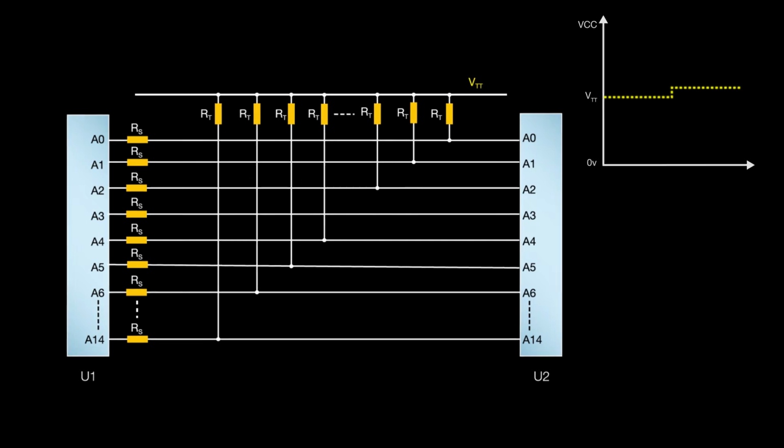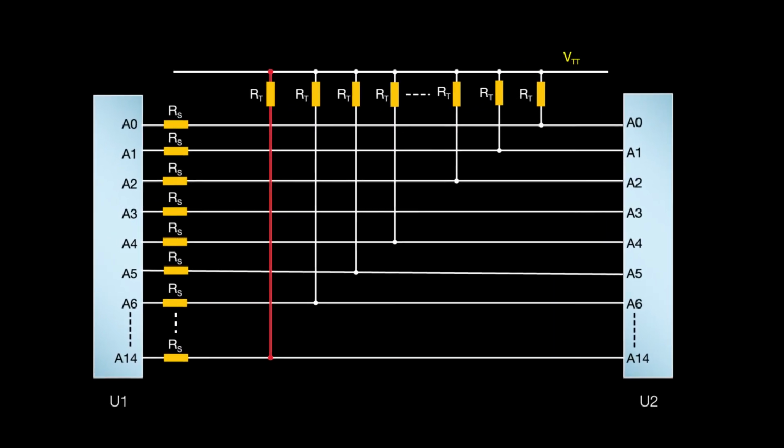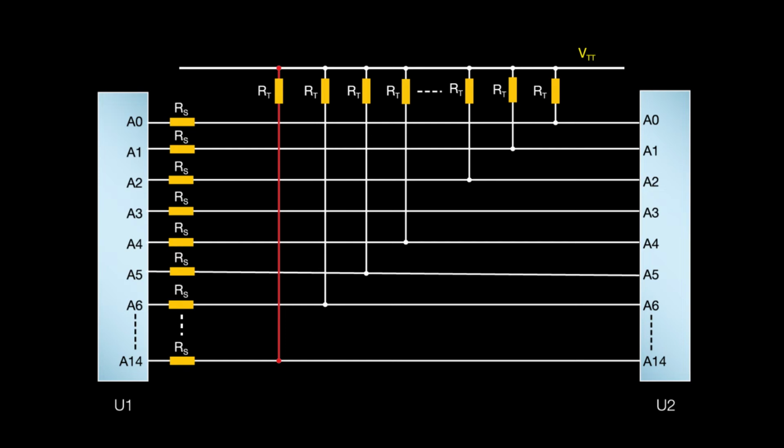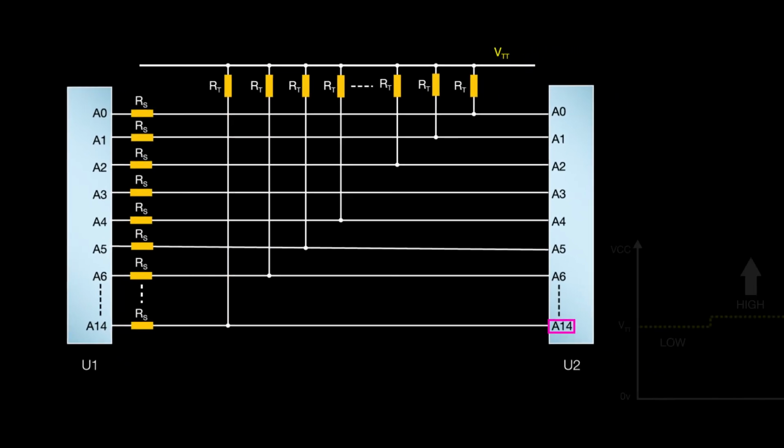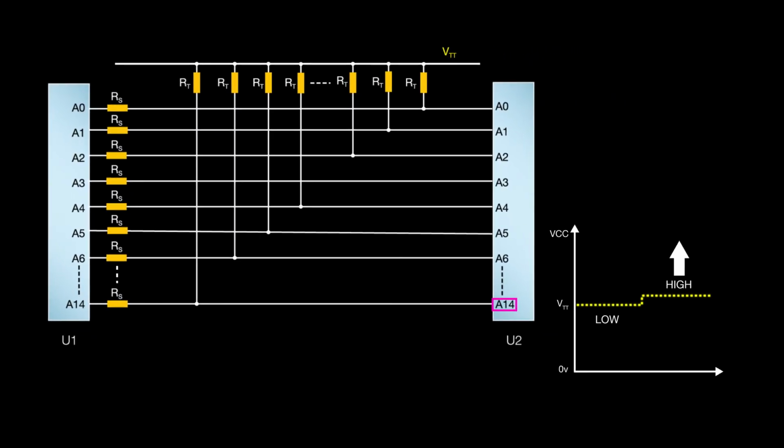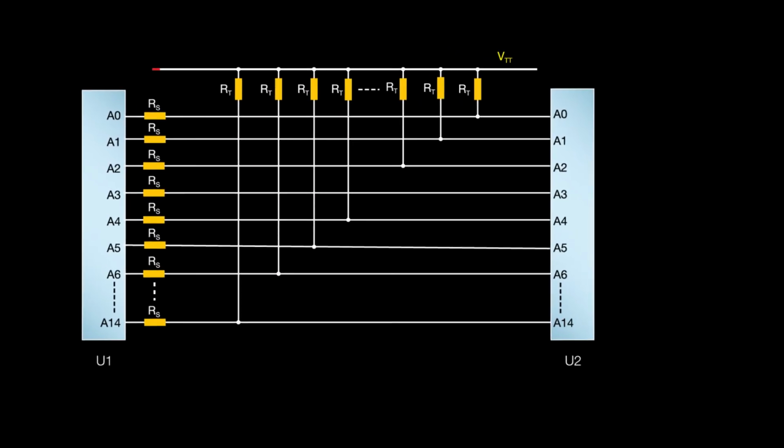Although that wouldn't be a problem for a normal power supply, here VTT sits mid-supply, so the small voltage change could be interpreted on the input that's being read as a change of state. That unexpected change would be incorrectly taken to indicate an assembly fault.